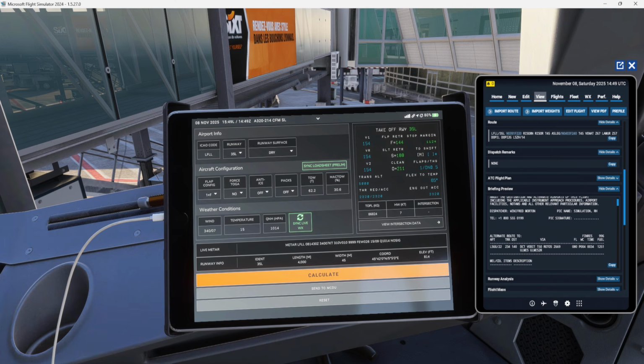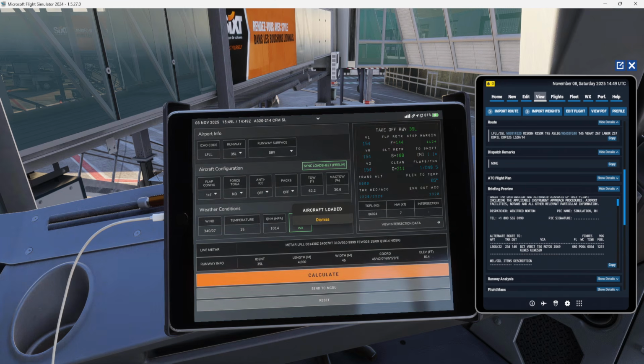Imagine you have a very huge fire in the fuselage. You have half of the fuselage with only fire. In this case, you continue? For sure, no. Abort the takeoff, even if you overshoot the runway. But in this case, you need to think, because if you overshoot the runway, you will have less damage than if you get burned in flight.